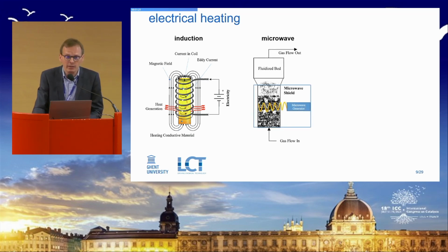Microwave is another technology that can be used, by generating microwaves and sending them through the material. Now, a potential downside with microwave technology, and again in relation to cooking, I think most have experienced already: if the food does not have the proper conductive properties, you have some hot spots and cold spots. So having an evenly distributed heating will quite significantly depend on the properties of the system you need to heat.